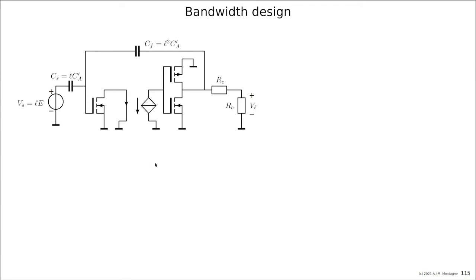And we are not going to sell these amplifiers, I promise you, but it's just for educational purposes that we do this one with an inverting current amplifier between the first and the second stage, knowing that this can easily be implemented later on with a simple current mirror. But you have the assignment to make this amplifier with a differential pair, and probably you will have much better performance than we do in this way.